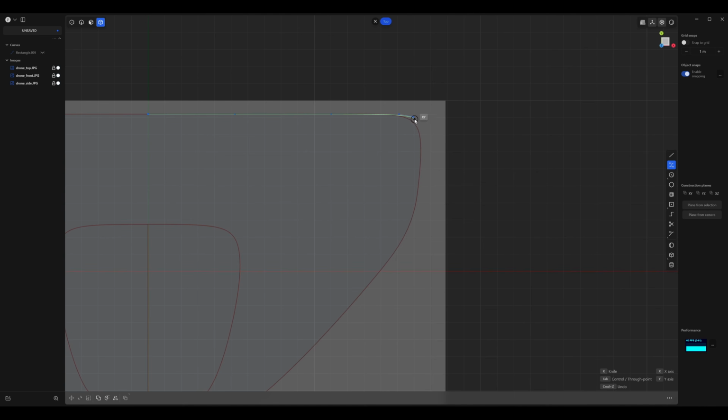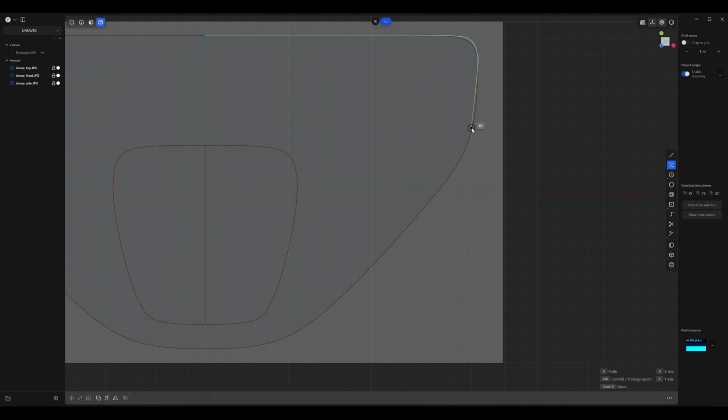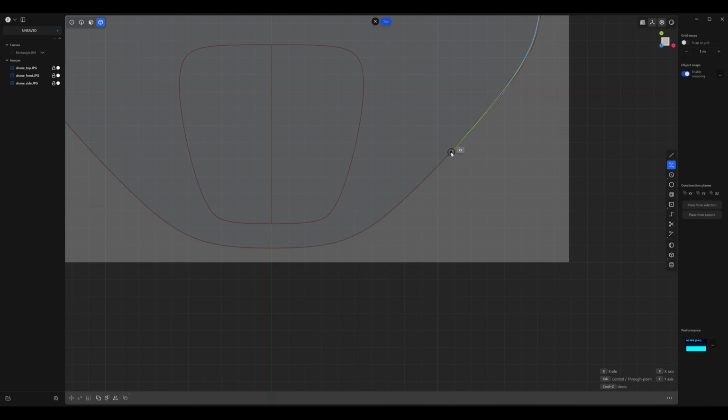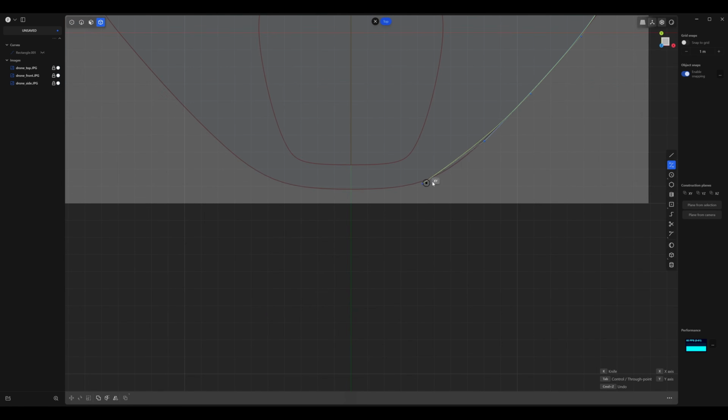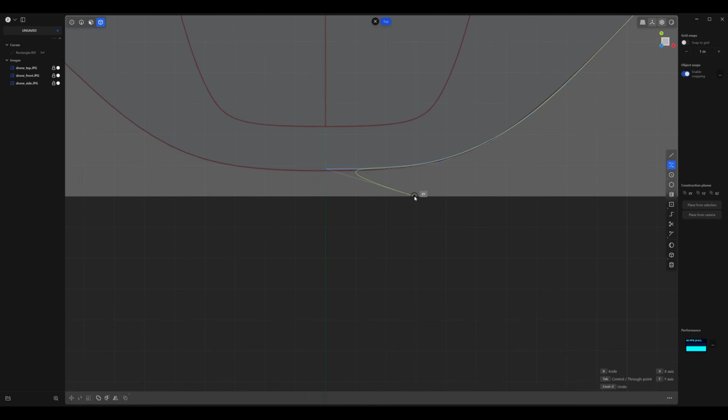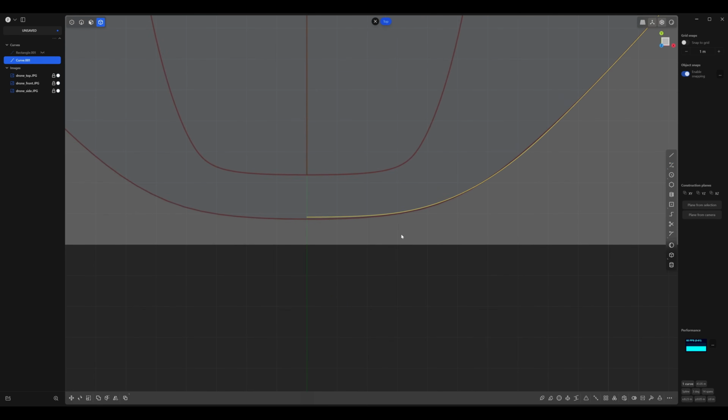And you can tell that I'm clicking outside because the CVs will kind of bend inwards. So you want to kind of create them like that, and we can adjust them later anyway. Again, we have a defined curve here, so I'm going to use 3 or 4 points. And the last one, again, they both should be aligned. And right-click to accept. I'm going to press 1 so I can go ahead and edit these.